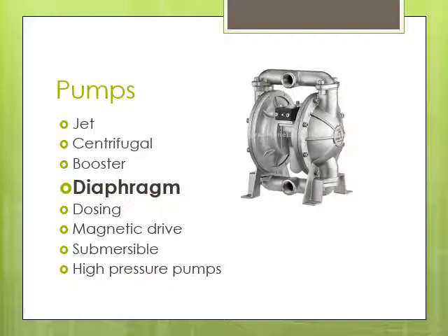Diaphragm pumps, you may see these on sprayers. These are typically used in applications where you're dealing with chemicals that might attack your pump components, so you don't want to have the chemical in contact with any metal.